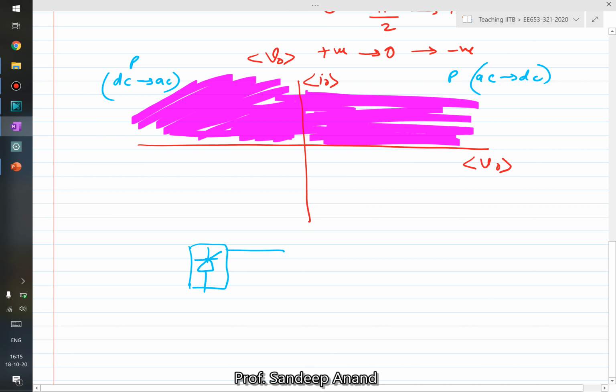And now in the output you have, let's say, a large inductance, which ensures current is continuous, and you have a battery here. And now you can regulate. So this voltage is V0. V0 is given by 2Vm by pi cos alpha. There is some resistance.